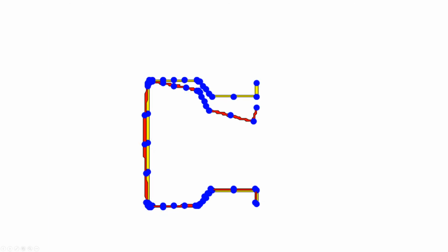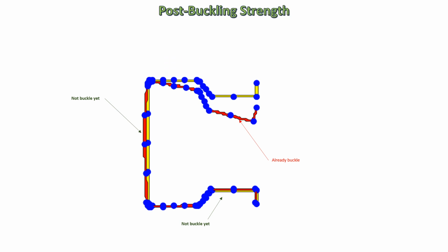It does not always mean that the structure will collapse right after local buckling occurs. In many cases, after buckling, the overall structural stiffness will be decreased but could still take some more loads as long as other parts remain stable. The strength of structure that surpasses the buckling strength is called post-buckling strength. In practice, most of the time, it is preferred not to consider post-buckling strength, and just provide the normal buckling strength higher than the loads required.